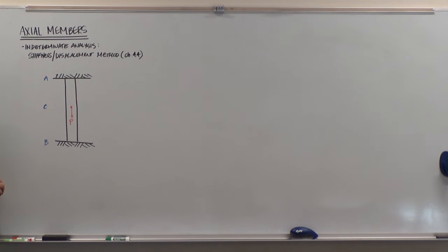We'll do a free body diagram of statics. It'll show us that we don't have enough equations to solve for the reactions or the internal forces here. And so mechanics of materials gives us the power to combine with statics another equation that also relates the forces in these members, not just based off equilibrium alone, but something that we call compatibility.